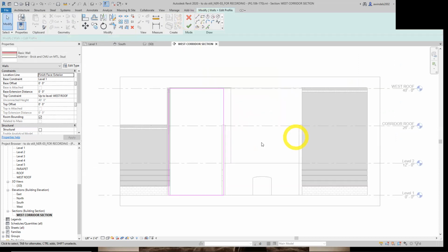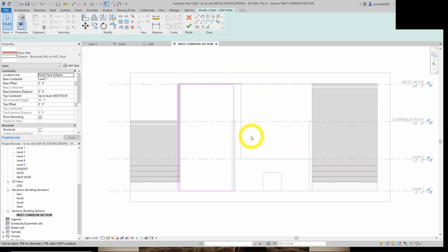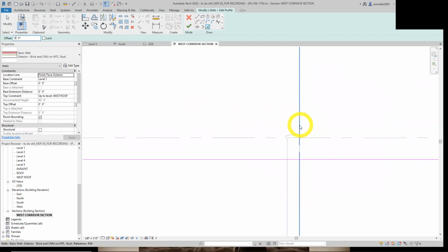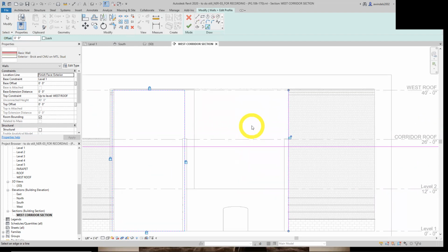Edit profile in sketch mode. And we're going to start by offsetting one wall to form this line in our sketch there. And we're going to keep this command active here. We're going to change the offset to 0. Select the inside edge right there. We're forming our shape. Modify trim. So making sure, yeah, that's the right one, the TR command. Let's hit that.